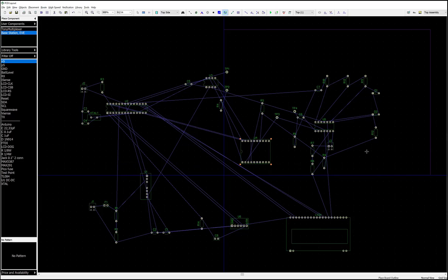There's a certain art in choosing the right size. If you choose it too small, you're not going to be able to auto route all your traces. If you choose it too large, it just looks large and ungainly. It's going to increase the cost of your project. There's many different layers here. We're going to have to move all these over onto our printed circuit board. You can't see the rest of the purple. It is a purple rectangle, but it's being hidden by the blue origin lines right now.